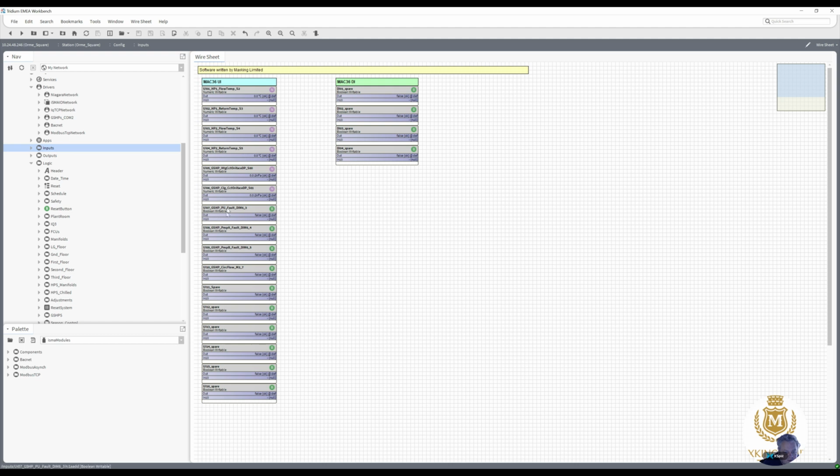Then from DIM 6.3.1 we've got the PU fault, so I'm going to take that straight from the trend into this controller on universal input 7. With it being a universal, it can be a digital input as well as a numeric or analog. And then DIM 6.4 pump A fault, DIM 6.5 from the trend, pump B fault.